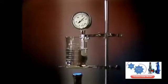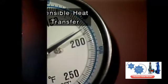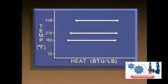A temperature change can be measured or felt. Heat transfer that causes a temperature change is called sensible heat transfer. Heat transfer that does not cause a temperature change is called latent heat transfer. At higher temperatures, the water molecules move more quickly than they do at lower temperatures, so it's easier for the molecules to boil and escape the water as steam. In other words, it takes less heat to change the water completely to steam. As the pressure and boiling temperature of water increase, the latent heat of vaporization decreases.